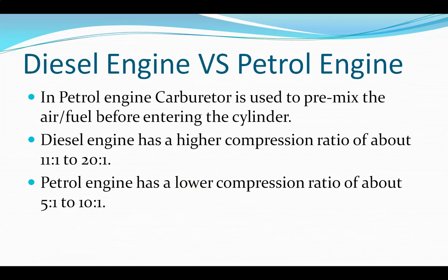And the clearance volume is the smallest volume to which the charge is compressed. So the diesel engine compresses the charge to a much smaller volume because it is only air that is admitted into the cylinder and compressed.